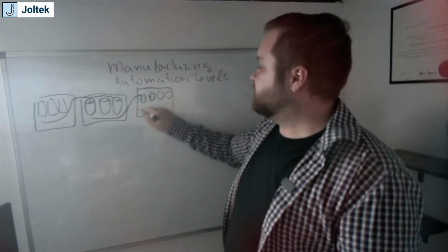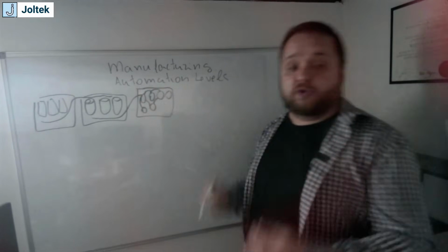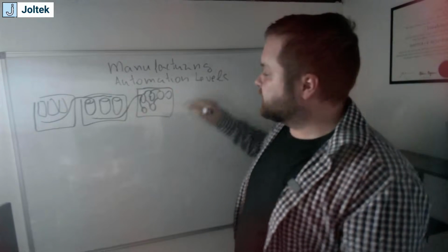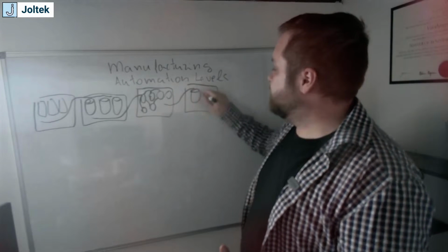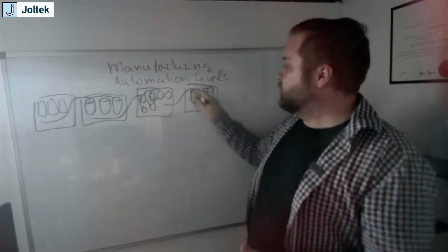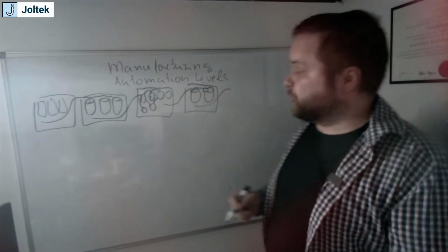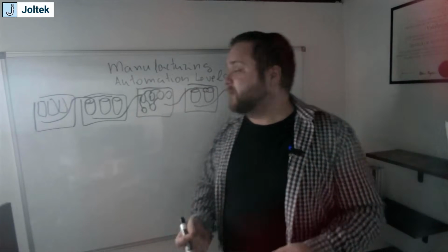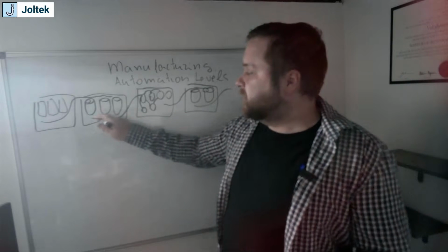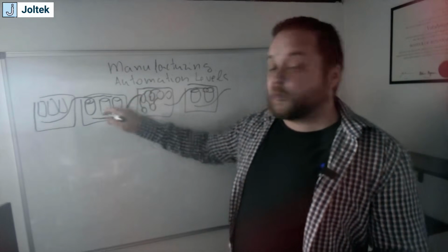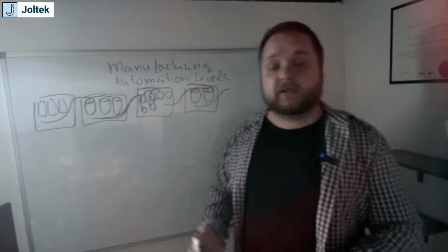And again, I'm going to draw this very crudely. There's going to be conveyors going in from the tanks. Between the tanks, it's going to be cooking, different batching systems. And so you have a system of systems, basically, where, for example, this is going to be the final destination of the batch, and it's going to be two large tanks from which this now gets palletized, for example, or packaged or distributed. So what you run into is, number one, you start needing to have interlocks, right? What is an interlock? This system needs to know when it can send product from the tanks into this batching process or cooking process or processing of whatever nature.